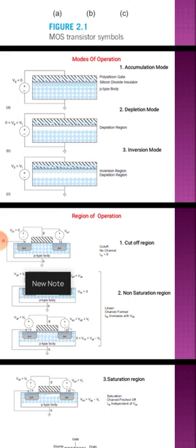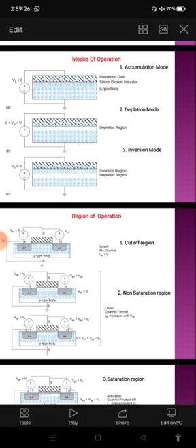And the third one is when we apply more positive voltage, beyond the threshold voltage. More positive charge carriers are introduced on the gate terminal. Thus, due to the capacitive effect, an equal number of negative charge carriers are introduced in the depletion region between source and drain beneath the gate terminal. So it leads to charge inversion. This is what is called the channel or conducting path.